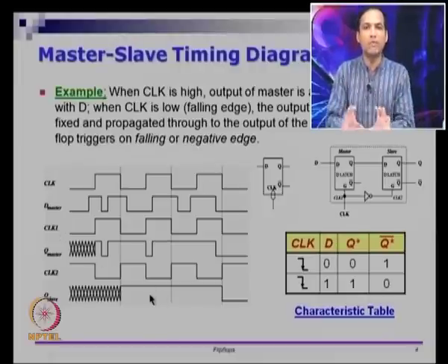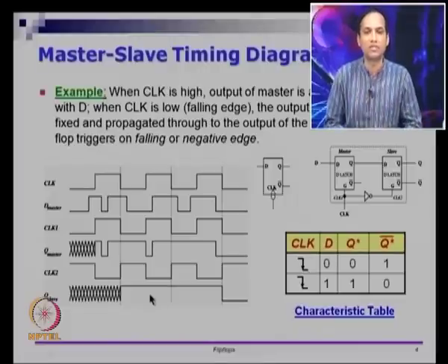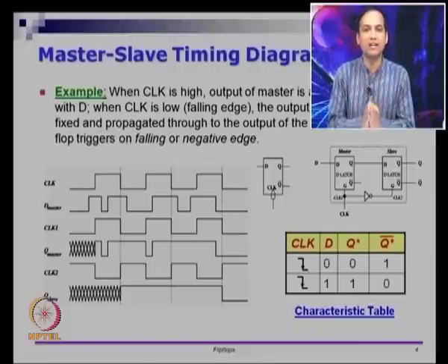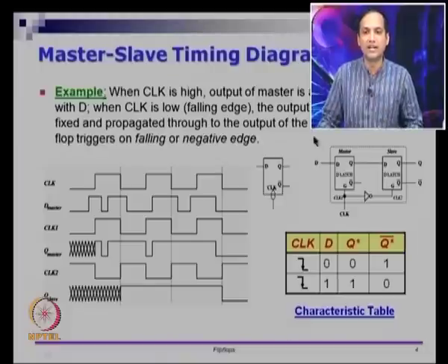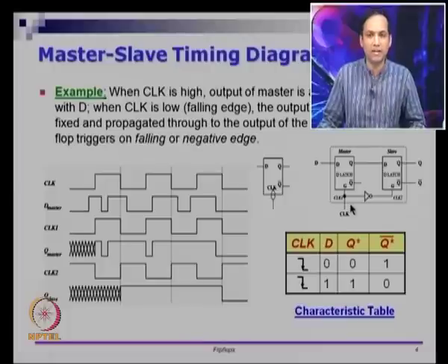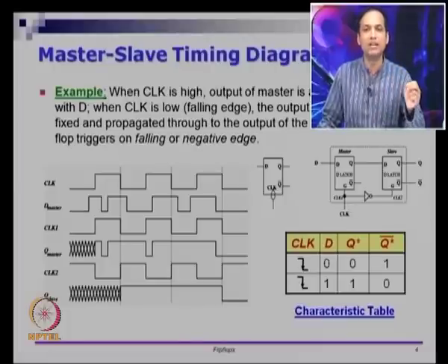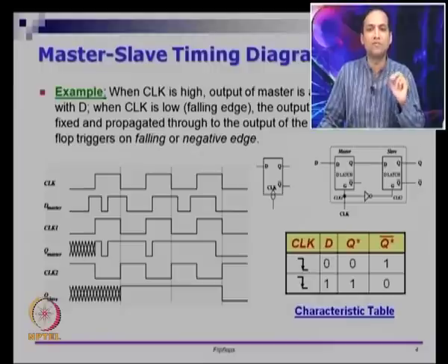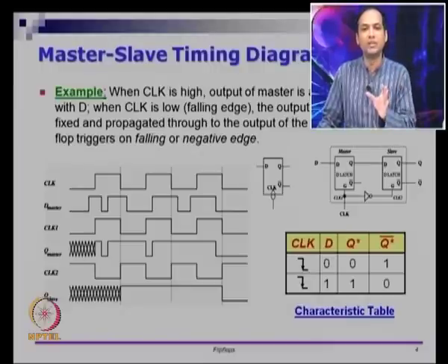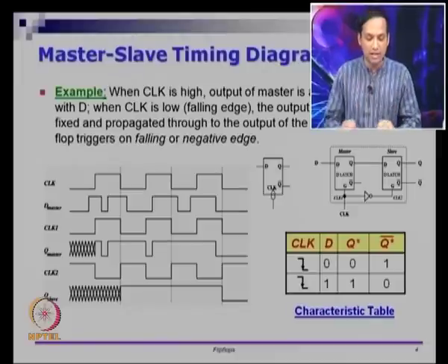So, I am now going to make a claim and we will verify that with the picture. The claim I am going to make is that this circuit that I did here, this overall black box, which I am going to call the D flip flop, is going to sample D only at the negative edges of the clock, and it is going to keep the value everywhere else. So, let me restate it.